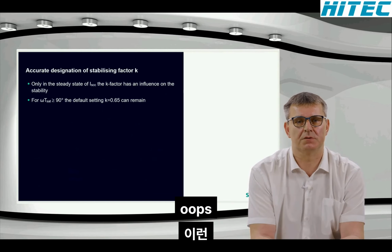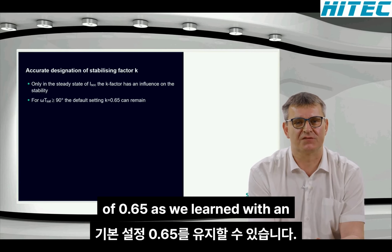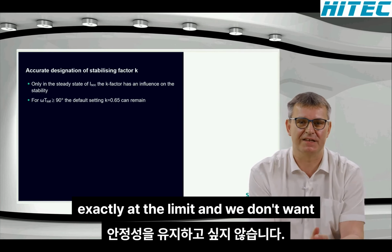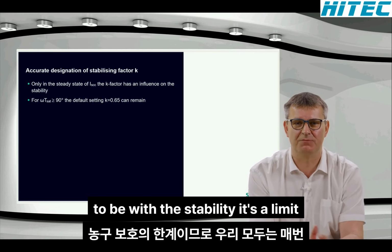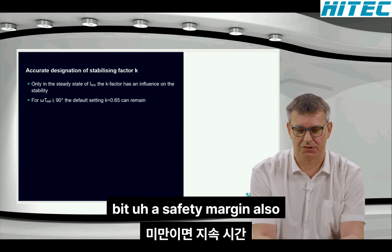We can remain with the default setting of 0.65. As we learned, with a stabilization factor of 0.5, we are exactly at the limit. And we don't want to be at the limit of stability with the busbar protection. So every time we have to calculate a little bit of a safety margin also.